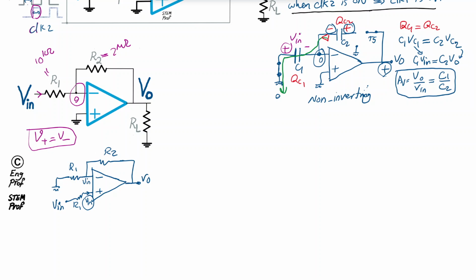There is a voltage drop to get to Vout, which if we just write the simple KVL for the voltage drop, we get Vout equal to simply 1 plus R2 over R1 times Vin, a positive gain basically. Vout over Vin as the voltage gain is 1 plus R2 over R1. So this is our voltage gain for the non-inverting amplifier.